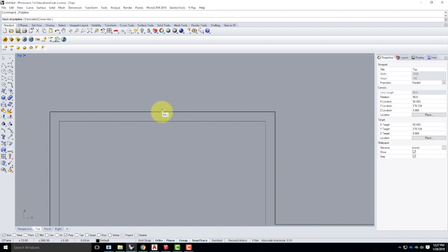So there it is, right in the middle of this wall, set to mid. And you see that when I have my object snaps on, I get a little white square that says mid in it. So I know what snap I'm using right now. So this is right in the middle of this wall. I'll click. I'll come down here. And now you see that my snap has two snaps, perp and mid. So I happen to have perpendicular snap on, so my line will always be perpendicular to the line it's connecting to.